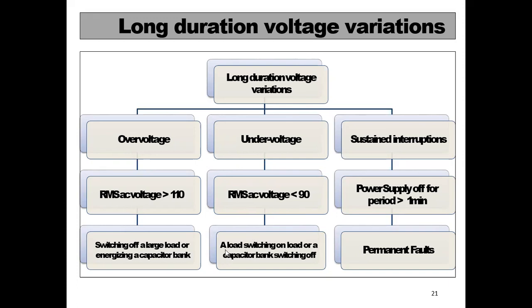This will occur due to switching on a load or a capacitor bank switching off. Due to suddenly increasing the load on the system, the voltage will be reduced.